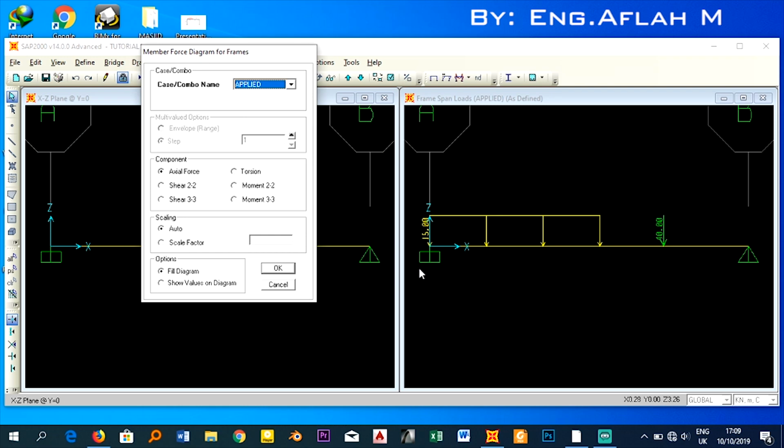Axis 2 is in the vertical direction, that is for the beams it is in the z direction, and axis 3 is in the horizontal direction, that's the y axis. Now our loads are in the vertical direction, so our shear that we are interested in basically is the vertical shear. So the vertical shear is in axis z, that's basically axis 2. That's why we say shear 22.